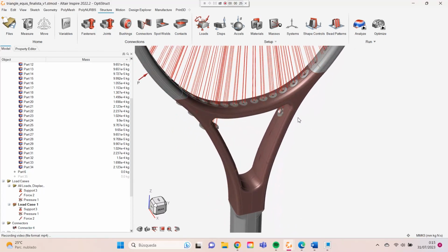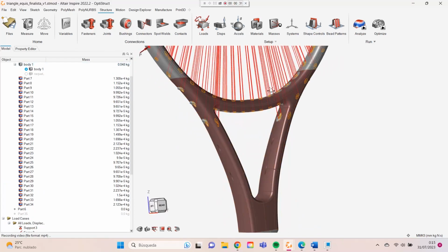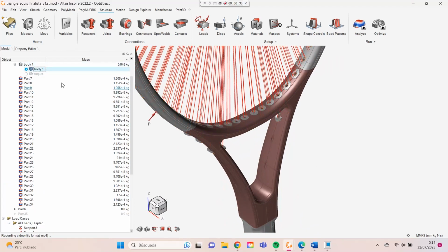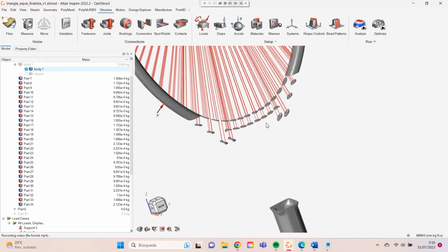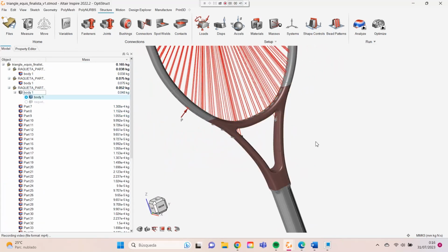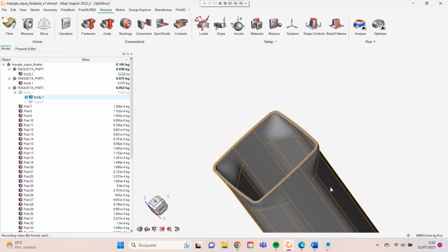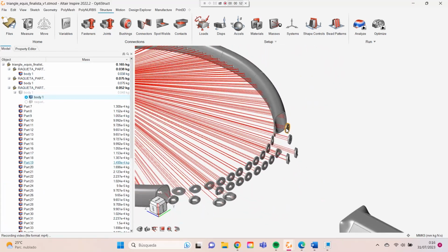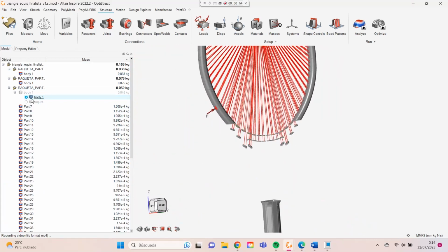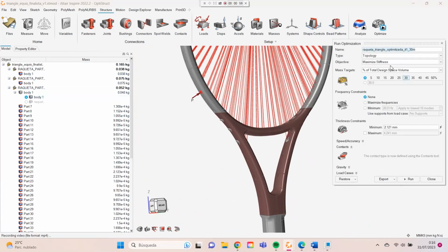Here, in the first model, this part was defined as design space. Also, 3mm partitions were made to keep the string holes in the structure, as you can see. All of that was done without touching the thickness of the whole racket, which means that it was not a solid object, as you can see as well. This was optimized by maximizing the resistance and maintaining a mass target of 30%.